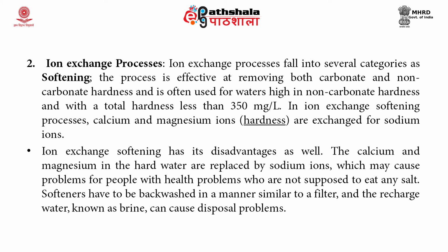The calcium and magnesium present in the hard water are replaced by sodium ions, which may cause problems for people who are not supposed to eat salt. The softeners have to be backwashed in a manner similar to the filter, and the recharge water, which is a brine solution, can also cause a disposal problem.